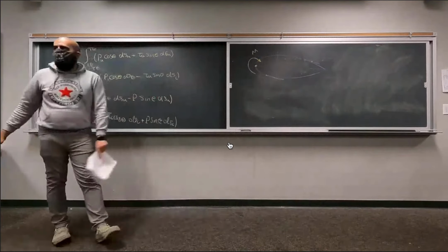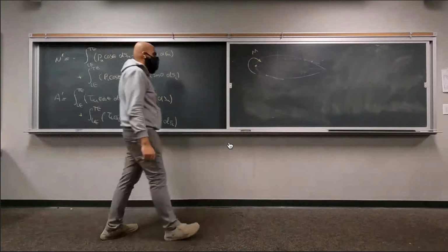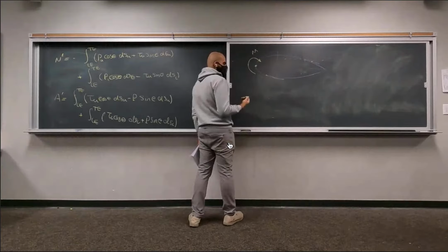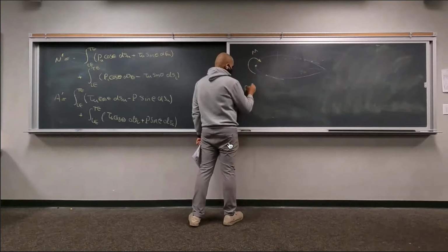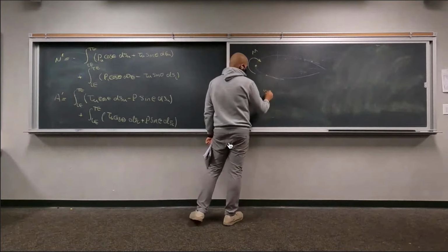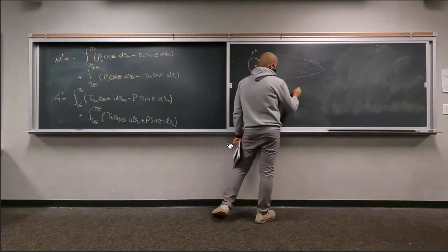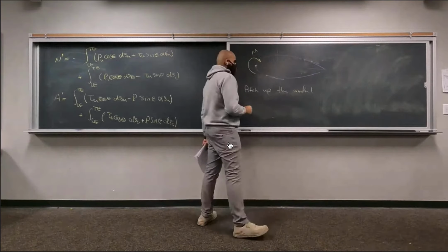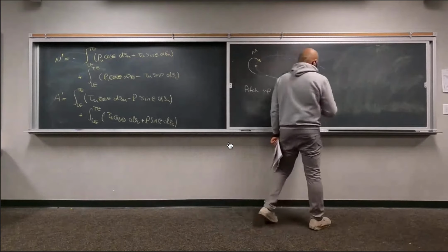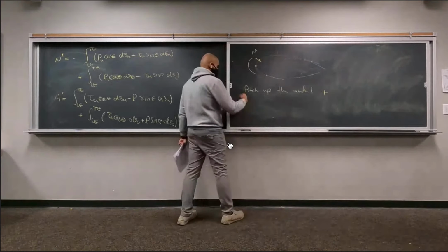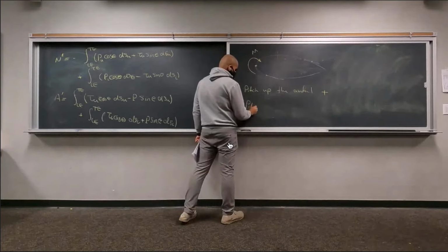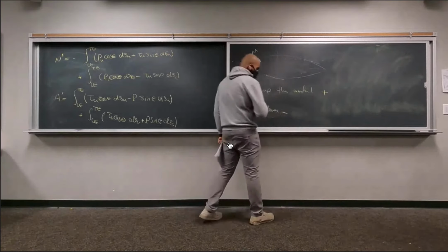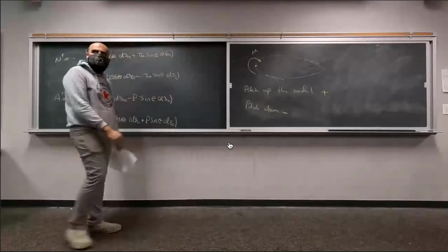And we should talk about the sign convention when it comes to moments as well. Whenever you have a moment that is going to increase the angle of attack, if you will, or it is going to pitch up the airfoil, your moment is going to be positive. And whenever the moment is in the other direction, which means that it's going to pitch down, your moment is going to be negative, right?